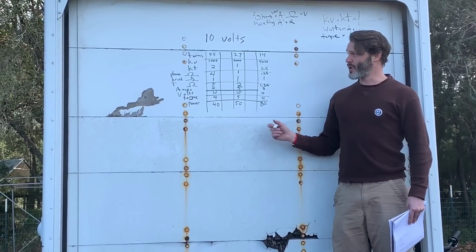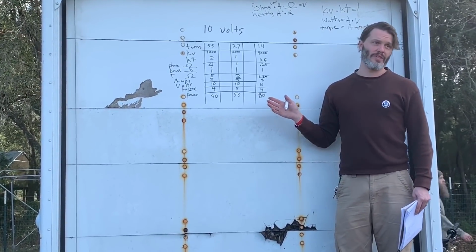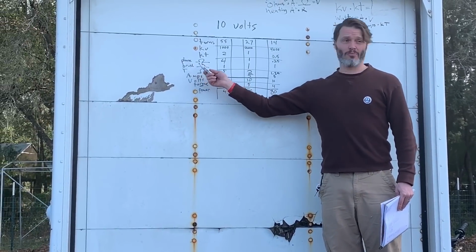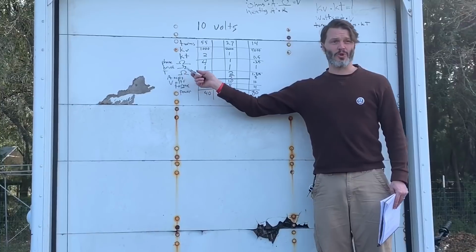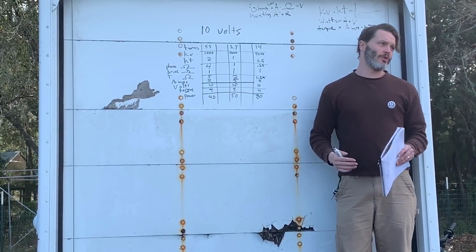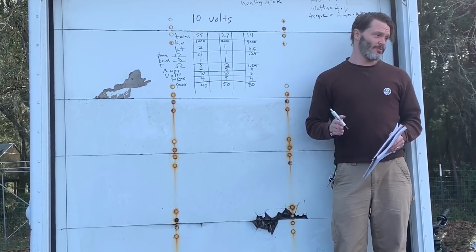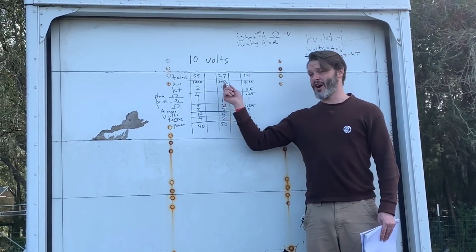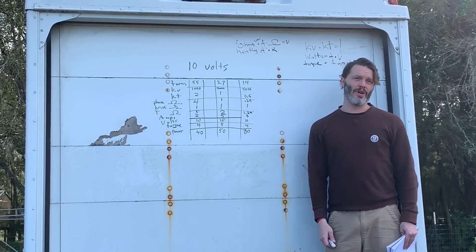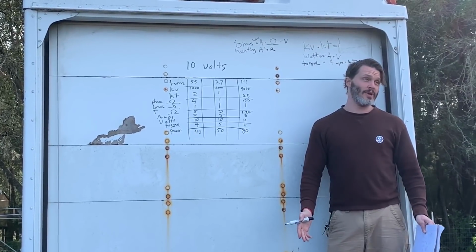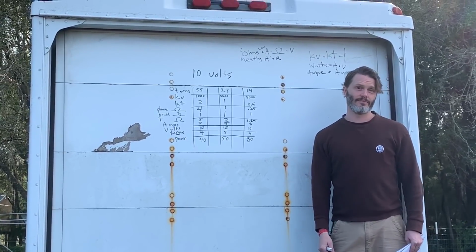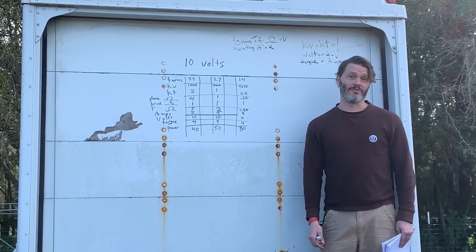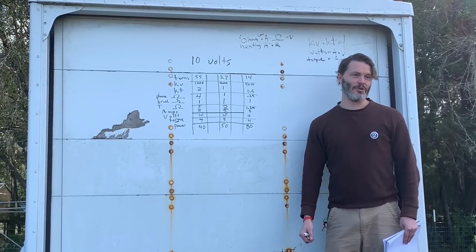And if you look, I haven't proven this with running the dyno, but what I am thinking is that when our phase ohms and our brush ohms are equal, that is when we're in the golden zone for a brush motor for producing torque. So it doesn't matter really what voltage you are applying to it, this is going to give us essentially our best overall results. Now from back in the racing days, does anybody remember what was said to be the highest torque motor when you're racing? Anybody used to be a racer? It's a 27 turn. It's almost like they kind of knew.